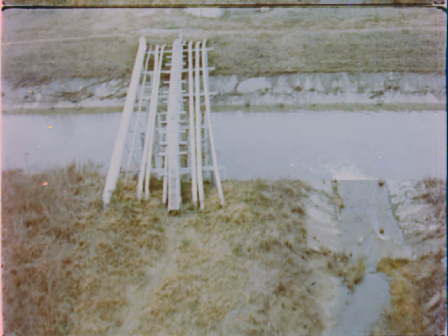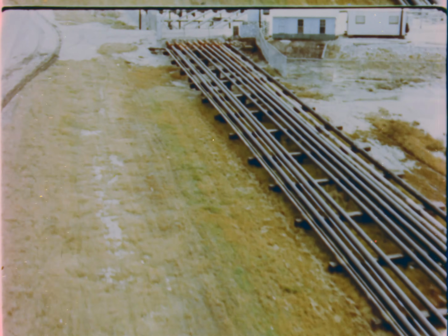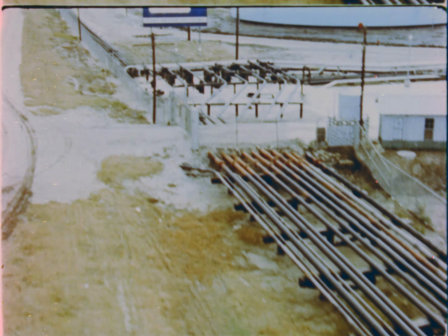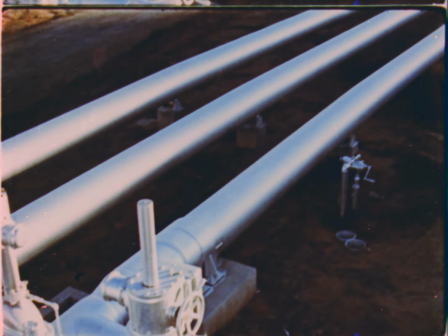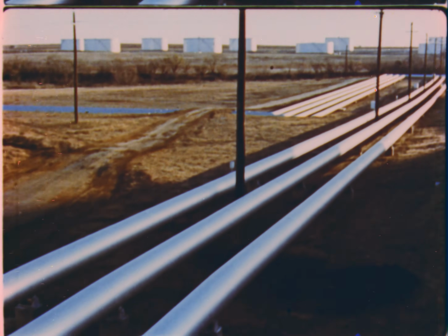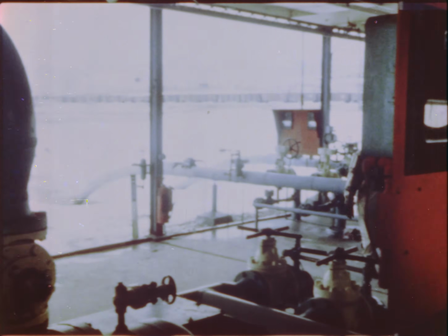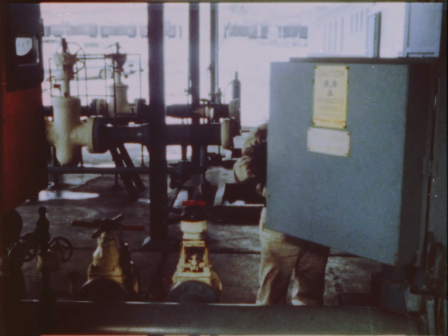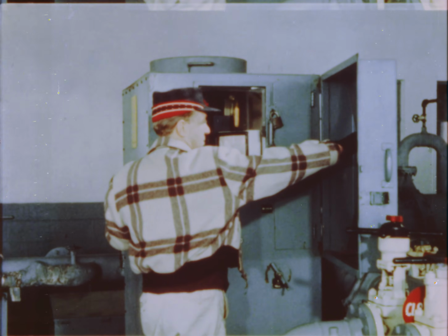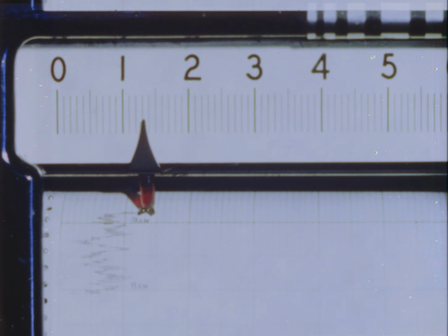Through the use of extremely low-level tracers, in proportions of less than a teaspoon to a tank load, it is possible to accurately separate shipments sent through hundreds of miles of pipeline. The injection of a small amount of tracer into the beginning of a shipment moves with it to a junction point. Here, at a point perhaps hundreds of miles from the origin of the shipment, an operator can determine its arrival as the tracer is picked up by a radiation detector. The minute amount of radioactive material of the tracer constitutes no hazard to the final product.